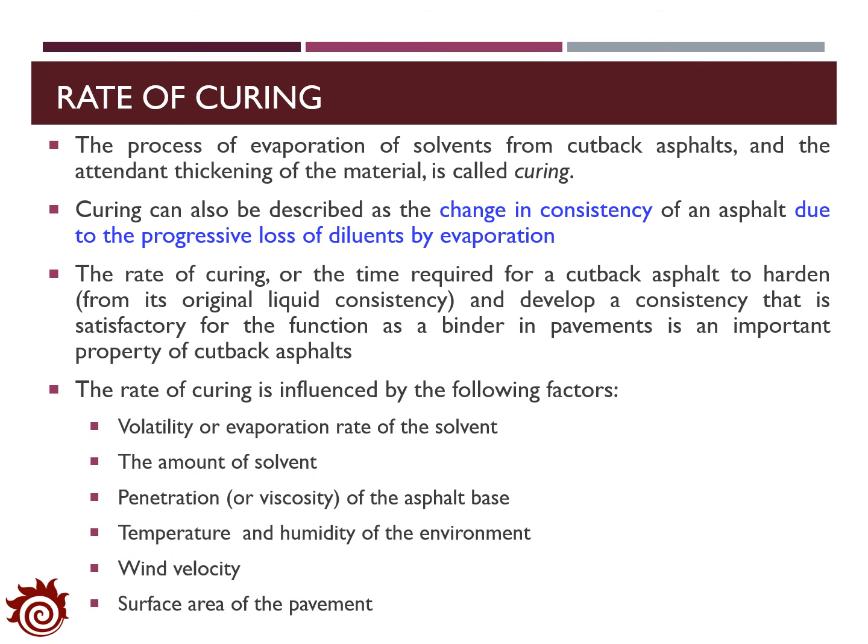There are a lot of factors that affect the rate of curing, and the page here shows a list of the important factors we need to consider, including volatility or evaporation rate of the solvent, the amount of solvent, penetration or viscosity of the asphalt base, temperature and humidity of the environment, wind velocity, surface area of the pavement, and so on.